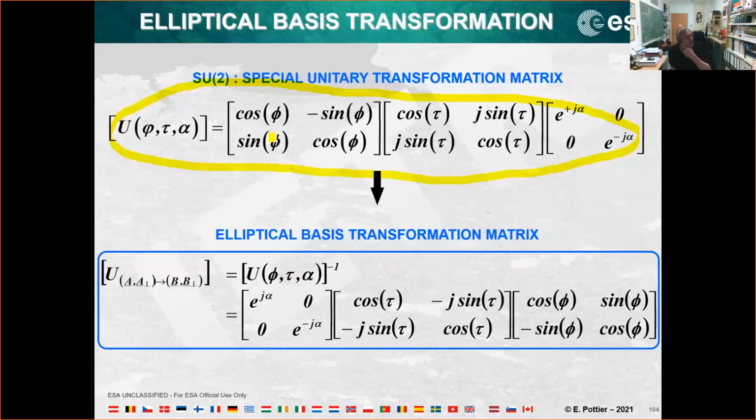With a new system, with RCM or RISAT also, they were able to integrate circular antenna polarization. So we know that today RISAT is using circular, RCM is using circular, ALOS-2 maybe, we don't know. They do some hybrid polarizations, meaning transmitting circular polarization. But remember that the easiest way to create an antenna is horizontal and vertical, and after you can do what you want with the linear processing.